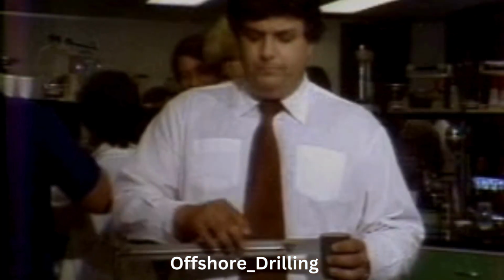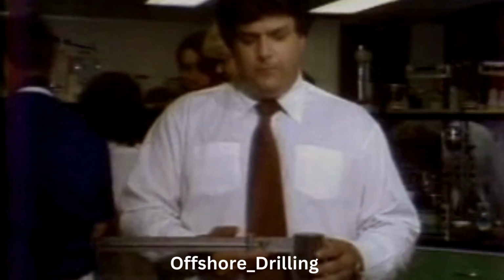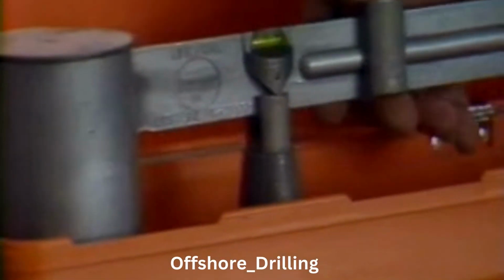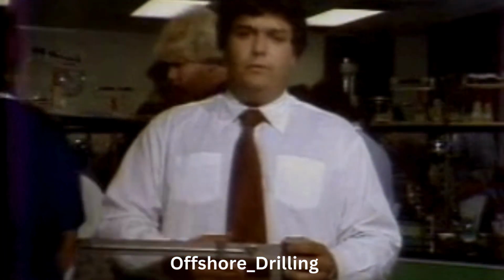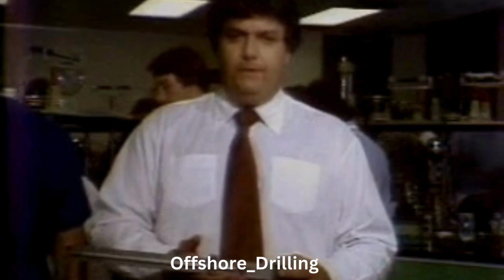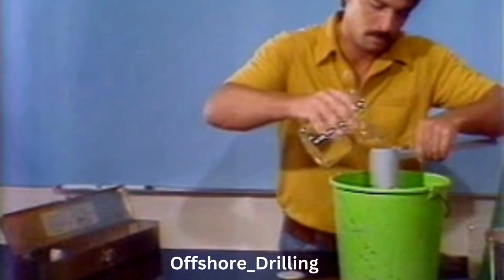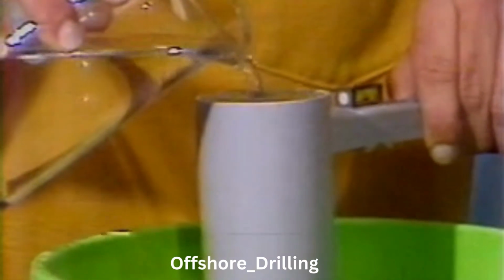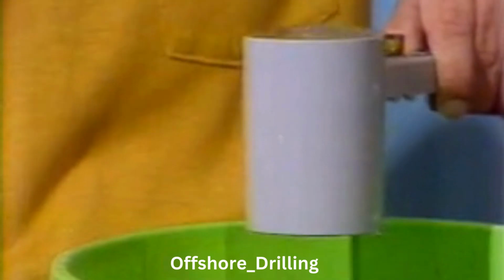The third point that one should make out is when weighing the mud, it is important that you weigh it dry. If you weigh the mud with only a wet bowl, a difference in the reading of the mud will be obtained. When checking the scales, be sure you use distilled water because it always weighs 8.33 pounds per gallon and can be used as a worldwide standard.